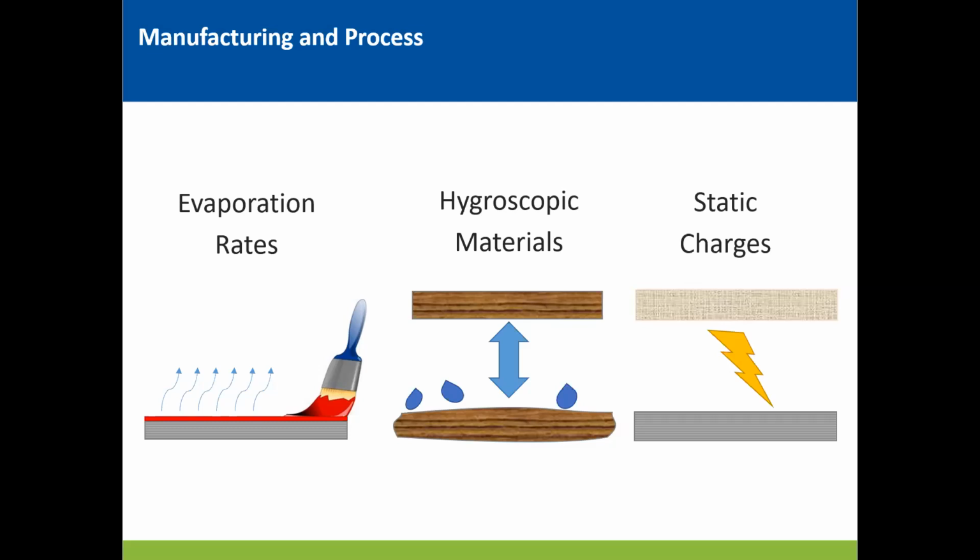And this can be problematic if we're talking about buildings practically. Hardwood floors are a common example that comes to mind. Many manufacturers of hardwood floors will invalidate the warranty below 30% relative humidity because they know that the floor will be prone to shrinking, and then you'll start getting the gaps and the creaks and the motion in the floor. So hygroscopic materials are something that we commonly discuss.